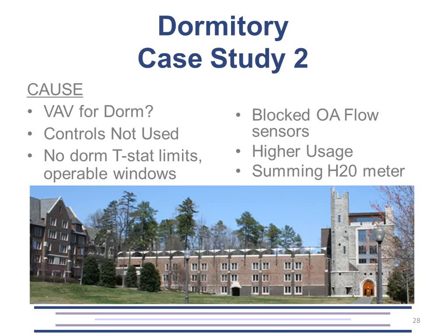There were a lot of common areas that were allowed to be used by the students, the residents, more often, or a lot more often, and for more hours per day than were originally anticipated. Some other things, with the operable windows, there was no lockout system that turned the heating and cooling off while those windows were open. And perhaps the biggest thing, the engineers were great in that they worked with us from